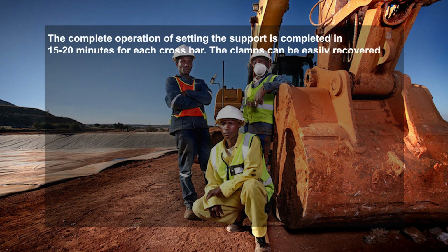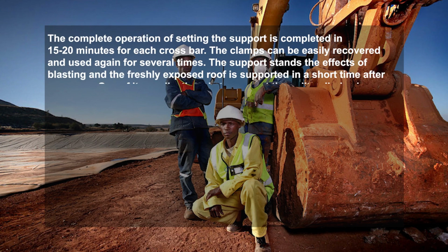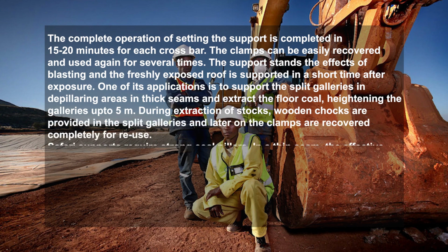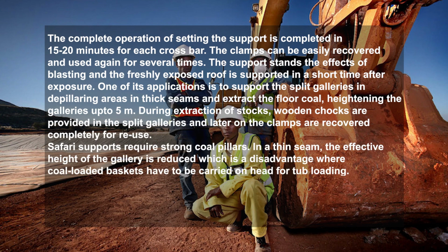The complete operation of setting the support is done in 15 to 20 minutes for each crossbar. The clamps can be easily recovered and used again several times. The support extends the effect of blasting, and the freshly exposed roof is supported in a short time after exposure.